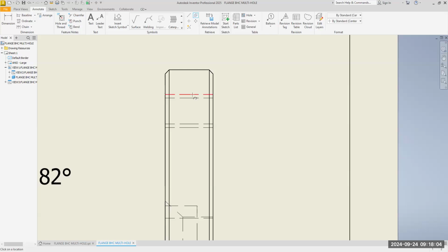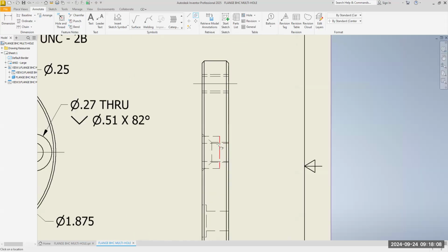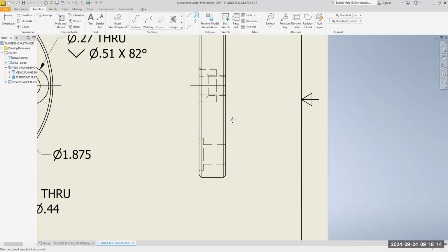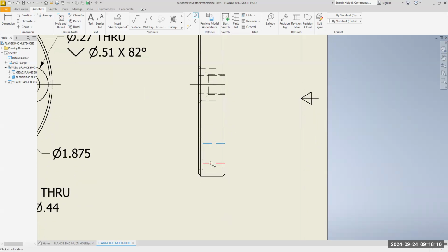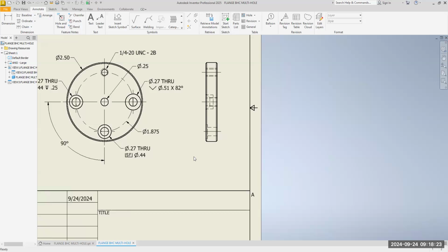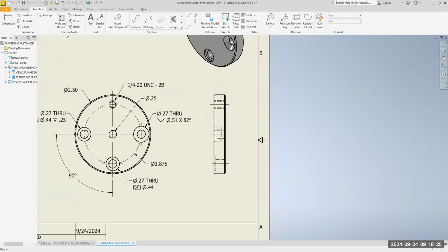And now look, click on this and this. It's going to put a center line there. By the way, a center line is not actually a part of the part. It just indicates the center of the hole. One here and also one here. Okay. I'm going to do a right click, cancel. That's good. All right. Now we're going to look at this hole and thread note.